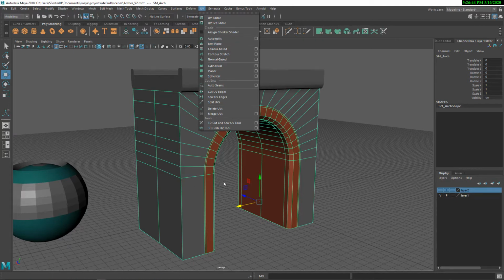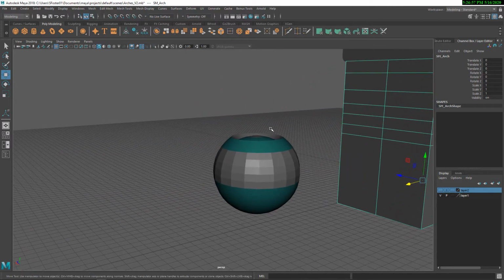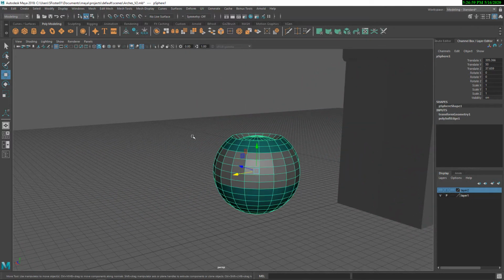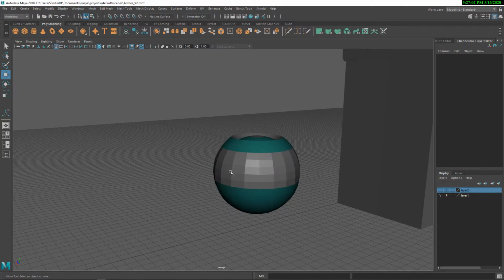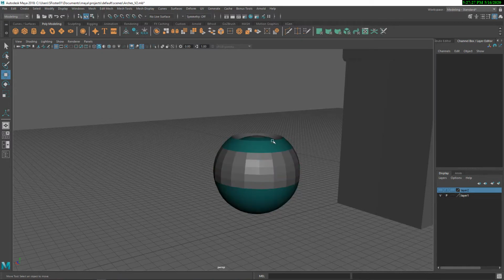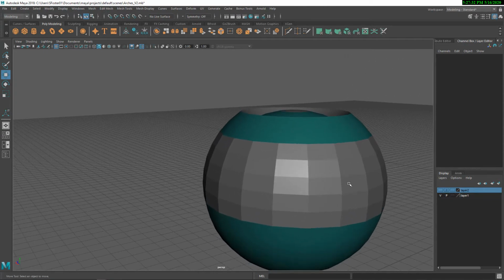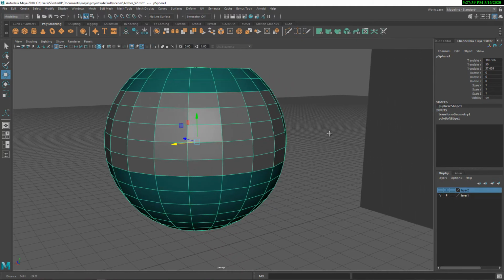All right. The next step I had was smoothing groups. Now, typically I will not use smoothing groups, especially if I'm using normal maps. Smoothing groups can fight normal maps because they are adjusting the surface normal, which is exactly what normal maps will do. So if I'm going to have normal maps on the object, usually I won't have smoothing groups. But if I'm going to have just this object, and in this case I'm not going to have a normal map, then maybe smoothing groups is something I'd want to do.